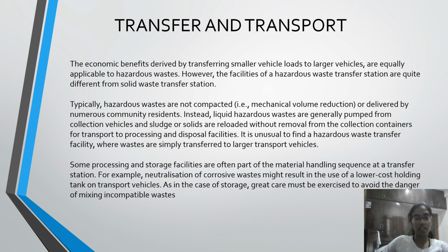Coming to transfer and transport, the economic benefits derived by transferring smaller vehicle loads to larger vehicles are equally applicable to hazardous waste. However, the facilities of a hazardous waste transfer station are quite different from a solid waste transfer station. Typically, hazardous waste is not compacted, that is, there is no mechanical volume reduction. Hazardous waste is also not reduced in size or delivered by numerous community residents, because it has toxic chemicals, so it should not come in direct contact with humans because it might cause health issues.